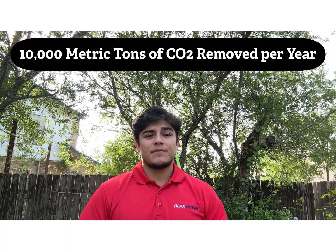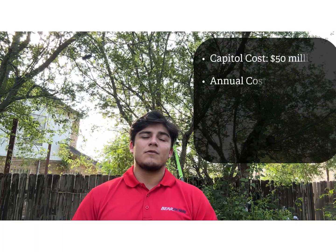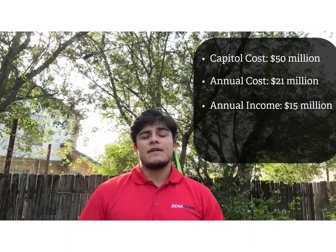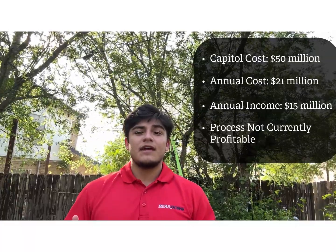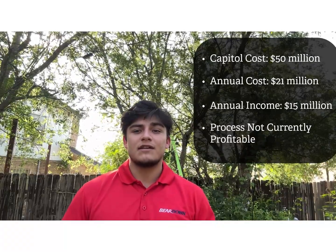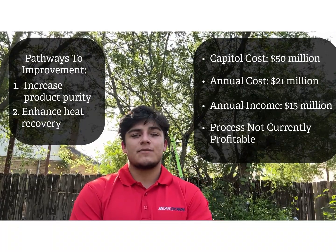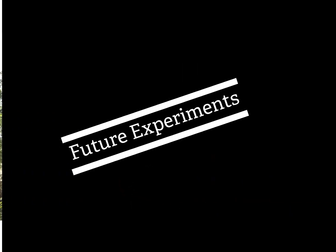From an economic standpoint, preliminary estimates indicate a capital cost of about $50 million and annual operating costs near $21 million. While high purity methanol can be sold across a range of prices, leading to annual income of about $15 million, the process is still not profitable due to significant ongoing expenses, including solvent replacement, heating requirements, and labor costs, which outweigh the revenue generated under standard bulk methanol market conditions. Potential pathways to improve profitability include upgrading the final product into a higher value specialty chemical, such as incorporating additives to produce chromatography grade reagents, as well as integrating heat recovery within the process.